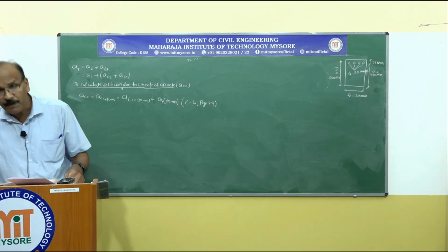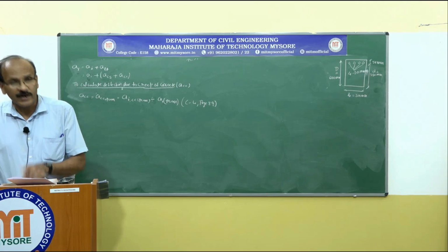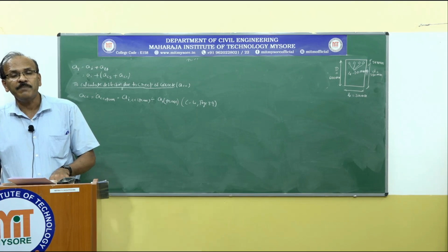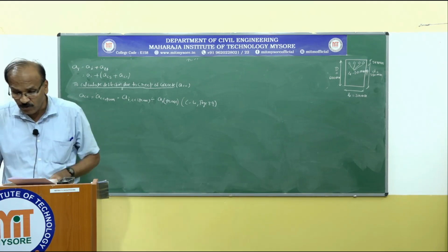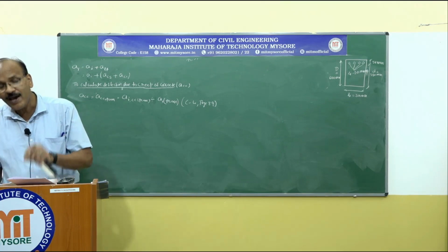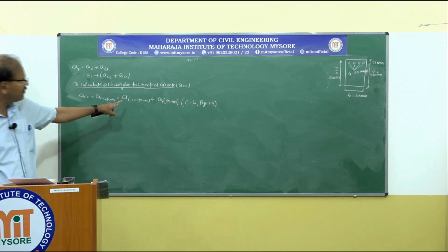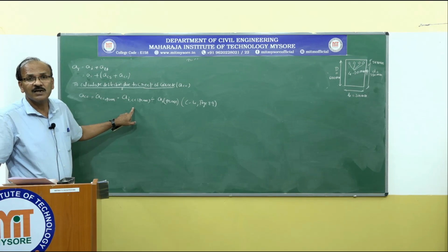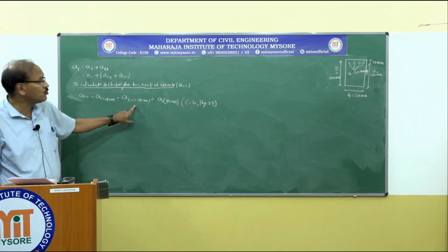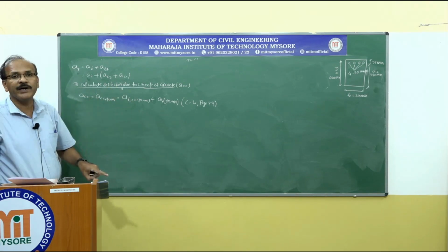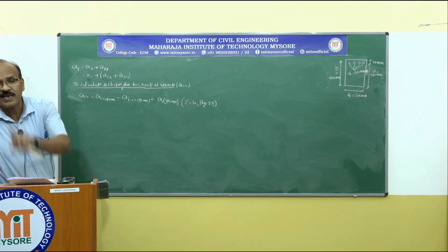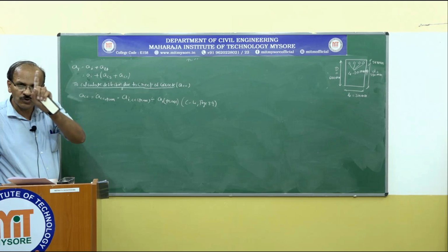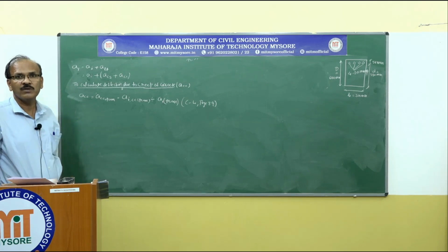One is ACC permanent, that is the total deflection due to creep due to permanent load, equal to AICC permanent, that is the immediate deflection and also the deflection due to creep under permanent load, minus AI permanent, that is the immediate deflection due to permanent load.